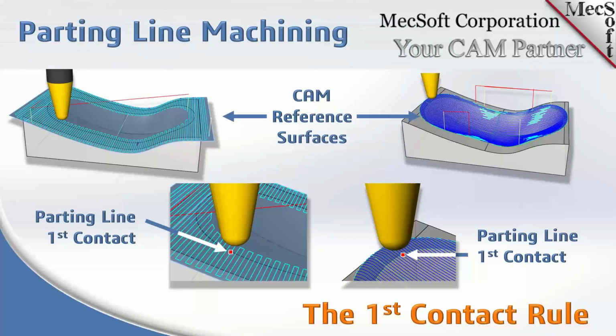So that tool will just say, howdy parting line, I'm going on my way. It's touched it and it's continuing to cut in other areas. It doesn't stop on the parting line. Like I mentioned, it doesn't roll over the parting line, and it doesn't roll along the parting line. And that's what these protection surfaces are used for.